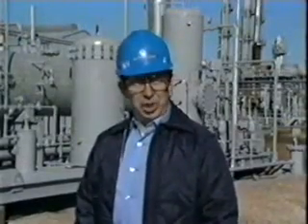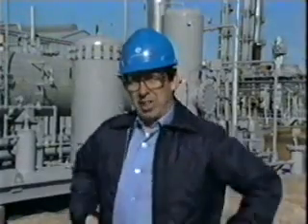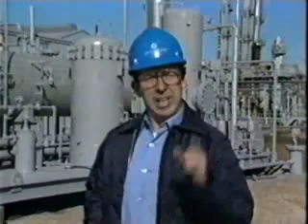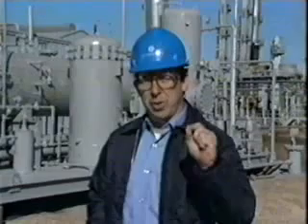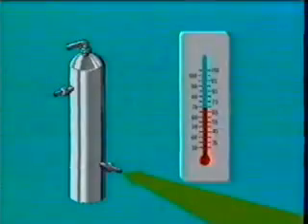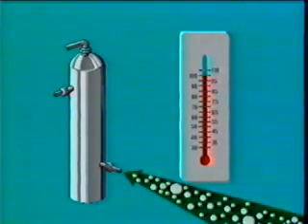Various temperature and pressure conditions affect how efficiently the glycol dehydration unit can operate. First, let's look at operating temperatures in the contactor, reboiler, and still overhead. Then we'll look at operating pressures. In the contactor, the temperatures of the inlet gas and the glycol affect the amount of water removal from the saturated gas. Now, if you recall, at constant pressure, natural gas can hold more water as the temperature of the gas increases. And what does that mean? Well, it means if we keep the inlet gas temperature low, the unit will have less water to remove from the gas.